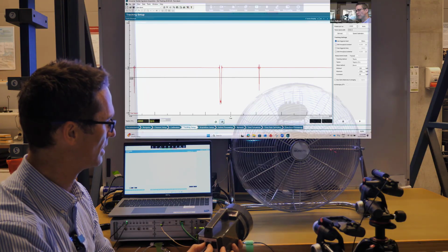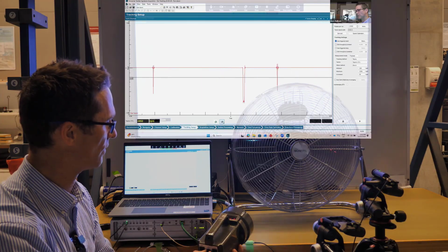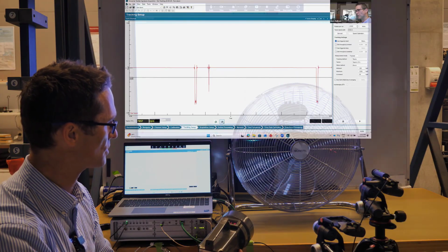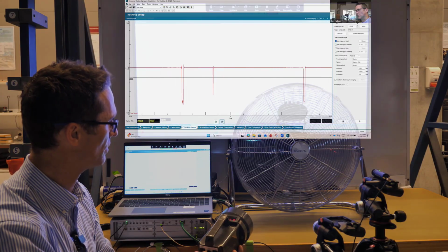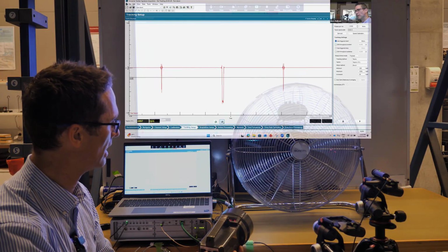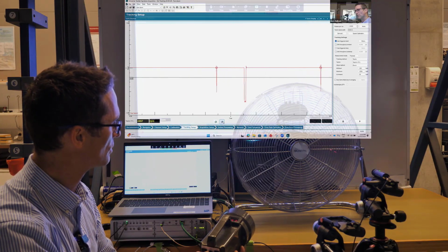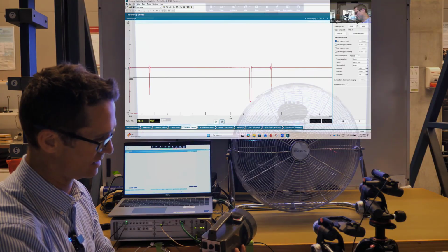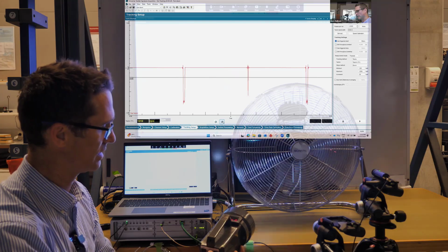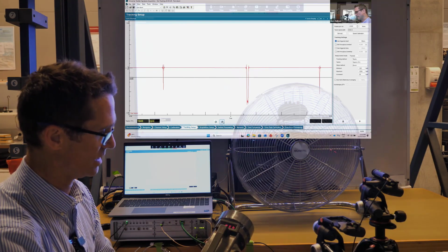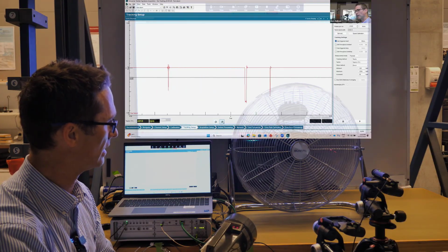It's a bit tricky because I don't have a way to define that frequency on the stroboscope. That's perfect. I'm just doing it with a fine adjustment, so there it is, approximately there. It's just gone past. I'm at exactly 1250, and then unfortunately this dial's a little bit sensitive. So you can see it sort of jumped to 1000 RPM there really quickly.